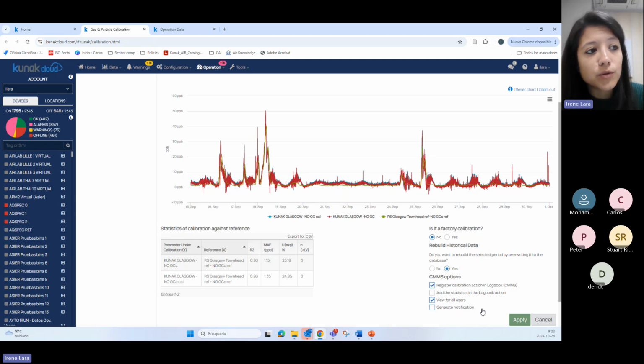What you can do is sensitivity. Sensitivity can be calibrated, but baseline, no, I don't recommend doing it. So basically we need a baseline calibration or adjustment every season. Yeah, that is what we recommend.